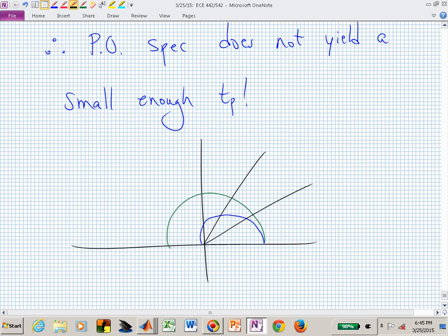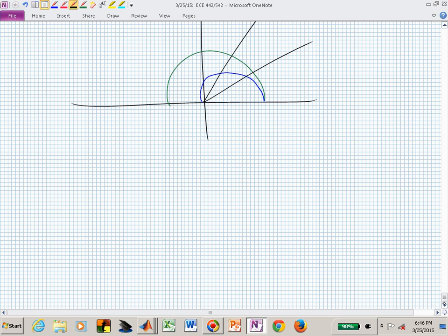If we now keep the same radius, but lower the zeta, that's probably not going to help us any, because that's going to actually give us a smaller angle. If you keep the same radial distance and go down on your zeta value, that's probably not the constraint that you want to start contracting. What you'll want to do to meet all three is to actually reduce the radius spec.